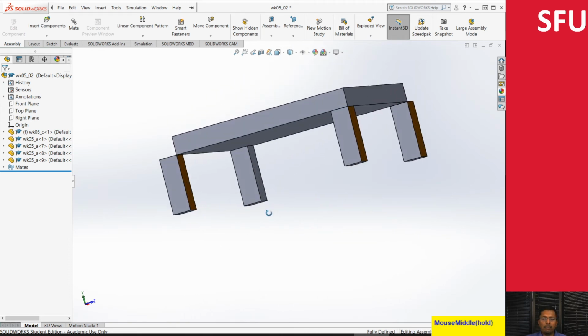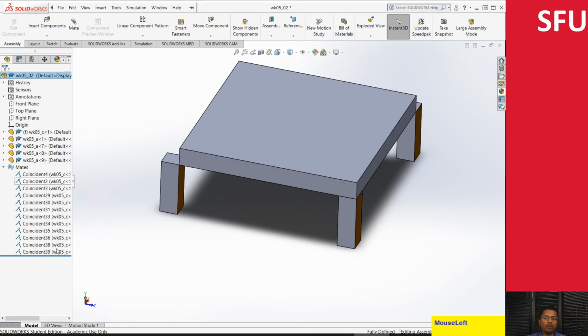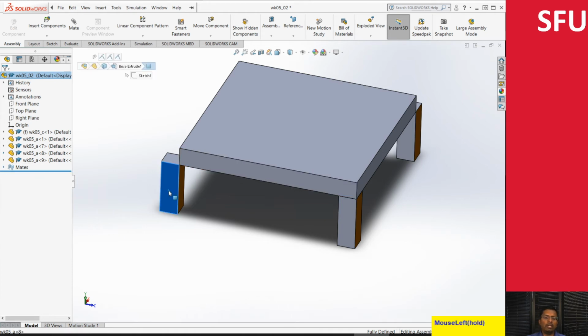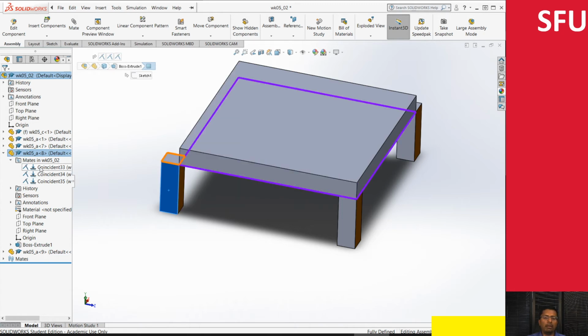So now I have a couple of legs which are outside my table, which is not that great for the stability. If I drop down, there seem to be too many mates here, which is a little bit confusing. Since I now only want to edit this object, I'm going to click on that object and it gets highlighted here, and we drop down and click on the mates and try to identify which is going to be the problematic mate.